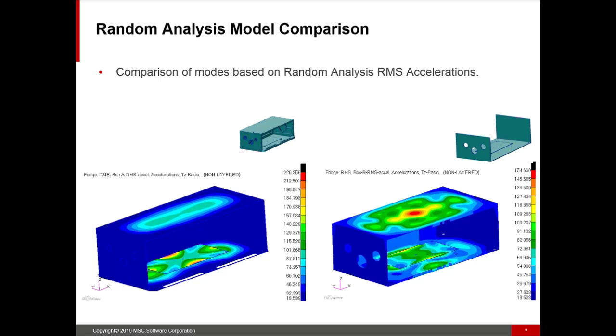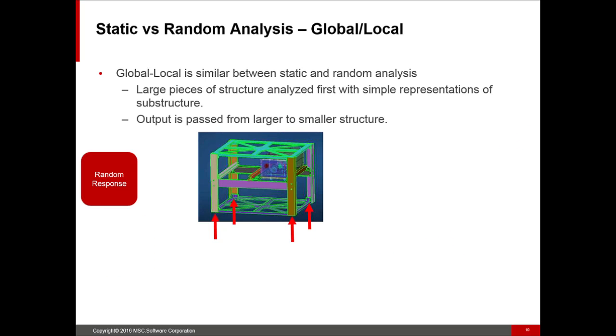The circuit board, again, we're seeing generally the same trends, but it's guiding us to where we might want to do something more to reinforce that structure and reduce the accelerations. We can also, again, look at stress or displacement. Generally, you'd be looking at stress to make a comparison between these two, where maybe the low-cost sheet metal box is going to get us in trouble, or maybe we can do some modifications to that to get it to pass whatever criteria we're looking at.